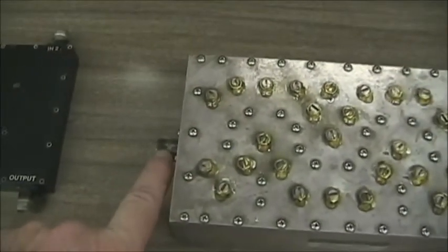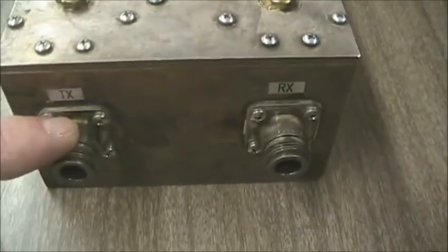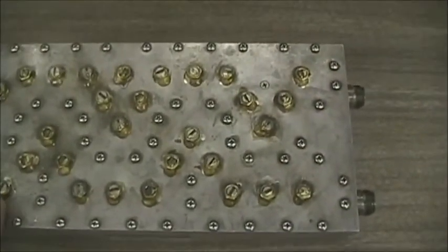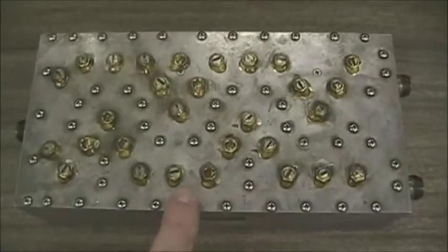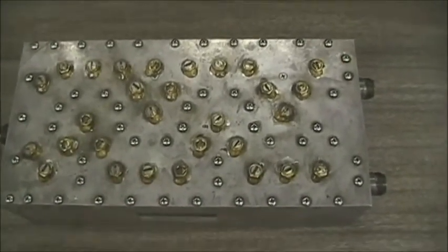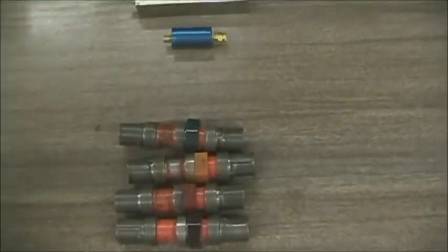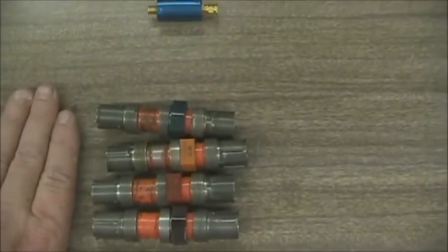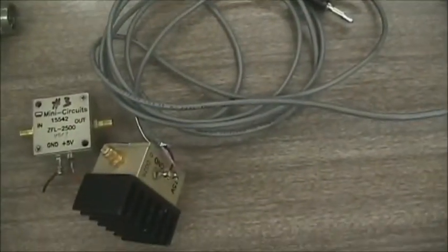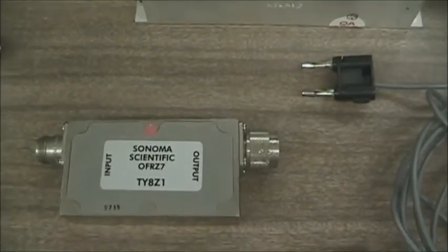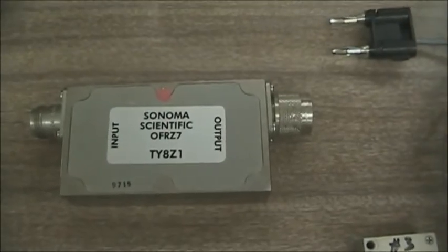So I would connect my antenna here, and then a transmit signal. I'll show that over here. The transmit signal's here, and the receive signal is here. I probably won't give you data on this, but it's 2 filters operating at different frequencies connected to a common device. So multi-port devices are also common, but we're going to focus on the 2-port devices: attenuators or loss elements, filters, different filters and frequencies, and then finally amplifiers. And I'll try and give you some data on the isolator, just so you'll get a sense of different characteristic curves.